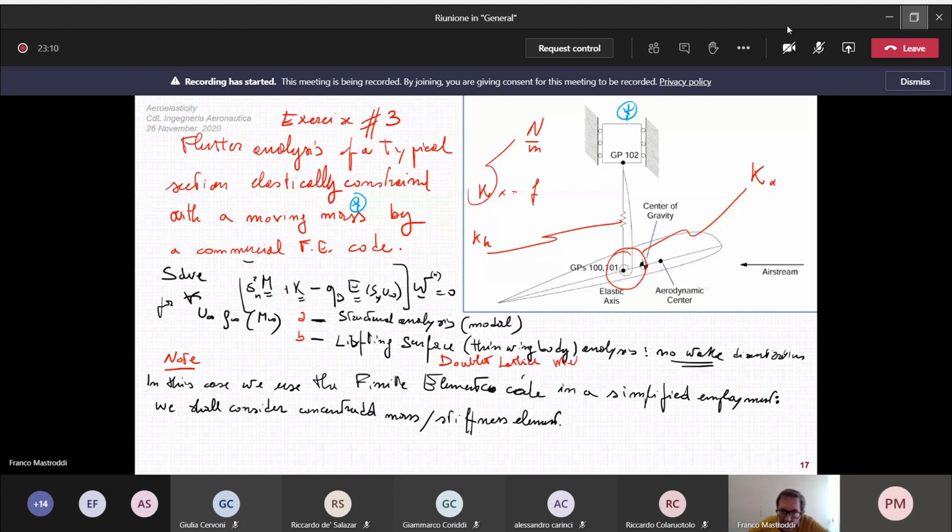Indeed, when you study the case of a very thin lifting surface, you see the integral formula for giving you the velocity potential or the downwash, you realize that the distribution of singularity is only reduced to a distribution of the phi on the n, what we called C coefficient or F coefficient on the wake, C coefficient.